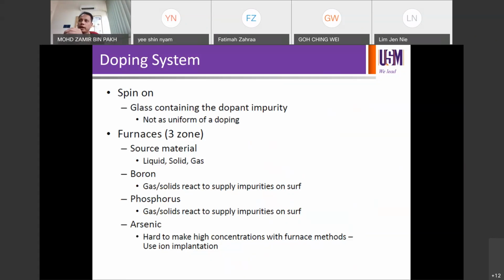Instead, we can also do that by some other methods. The method I mentioned and showed just now is the gold standard method. You can also do the diffusion process by another technique. You can use spin coating, particularly if you are working with silicon with circular shape, it's easier to spin on. So you can actually spin on, and then you can also use phosphoric acid, H3PO4.